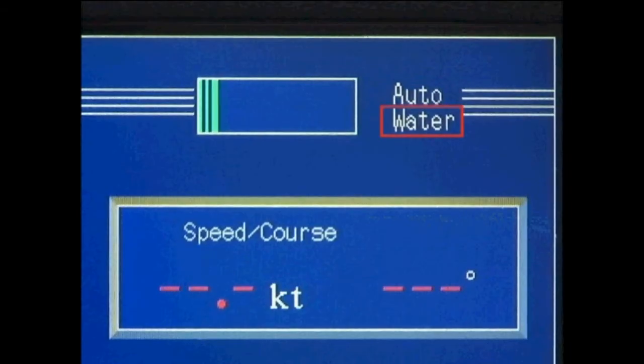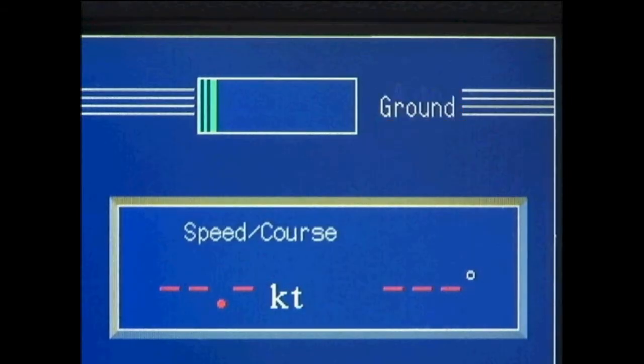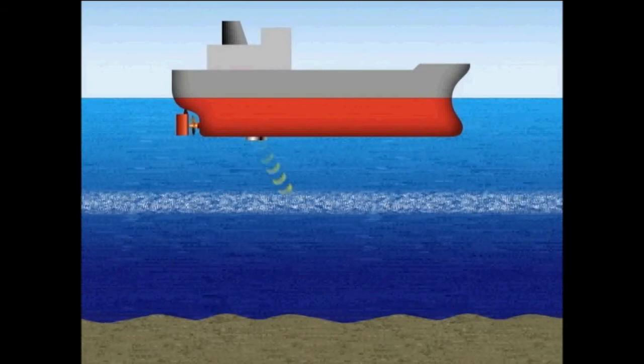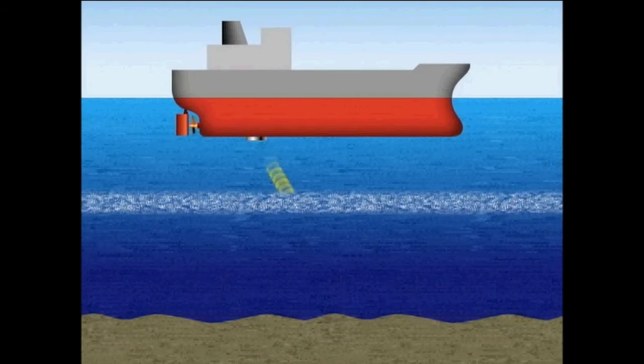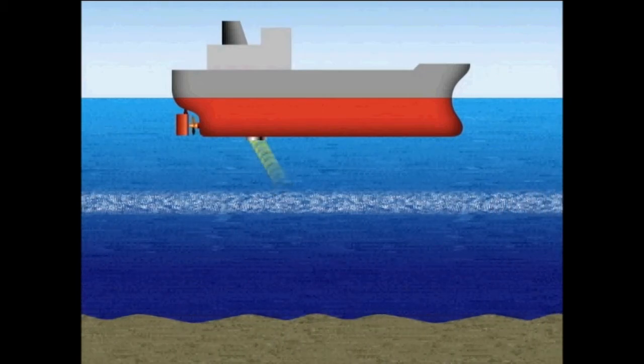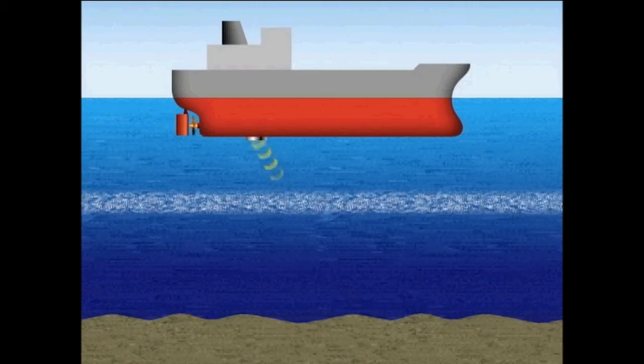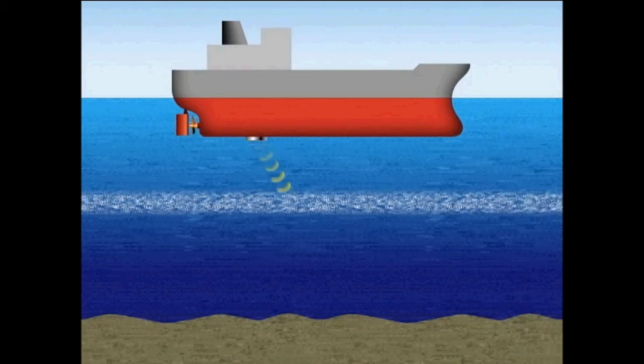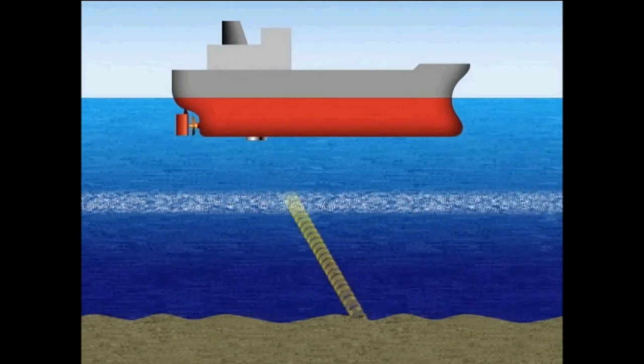The Doppler sonar speed log has two modes. One can measure speeds through the water and over the ground, the other through the water only. The EM log can only measure speed through the water, but the Doppler sonar speed log has the ability to measure speeds both through the water and over the ground by switching between the two systems.